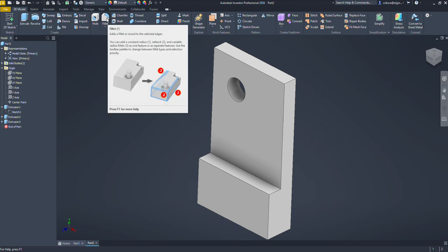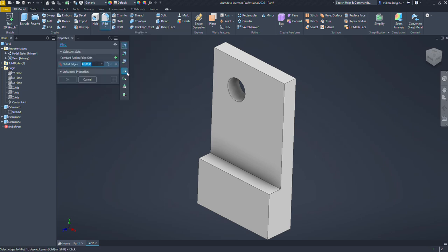Notice there's a fillet tool. Go ahead and click on fillet. And over here we could set a radius or whatever size. Like let's type in 1 inch, or just type 1. And now click on this edge here when the edge highlights. And it's like you hit it with a file and you file it down to round it off. Now you could adjust it. See that little arrowhead? You could move it in and out. And so that's what I talked about with your creative side. If you can't get it back to 1 inch, go ahead and just type it in.